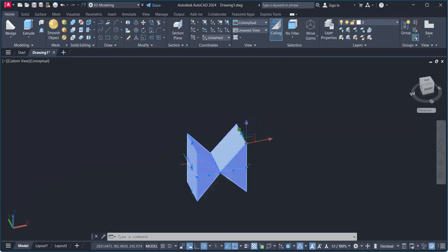If I want to rotate, RO enter for rotate, and select this base point, and then I want to select here. Then I rotate this portion, not the above, not this X section. I just rotate in this X and Y direction only. Okay, not the Z direction. If I want to rotate in the Z direction, I can't rotate it. But how can we do this for this part?